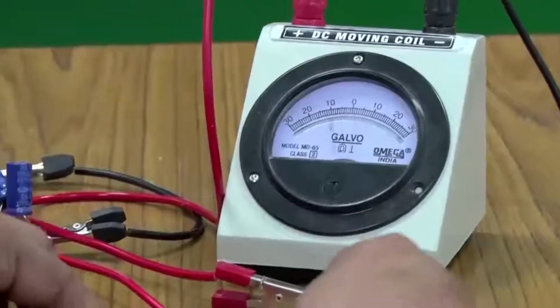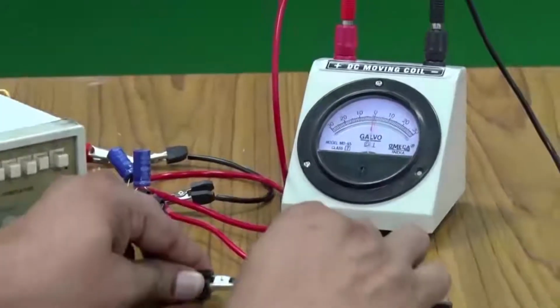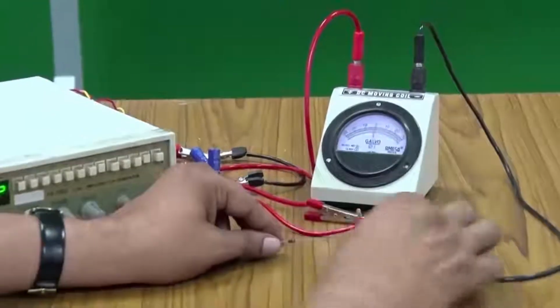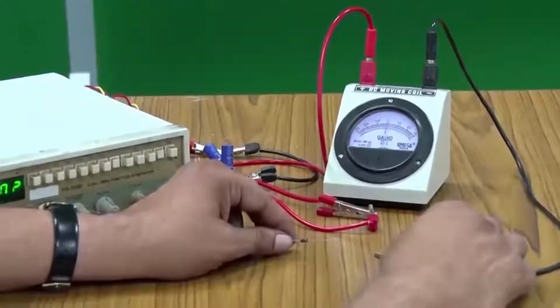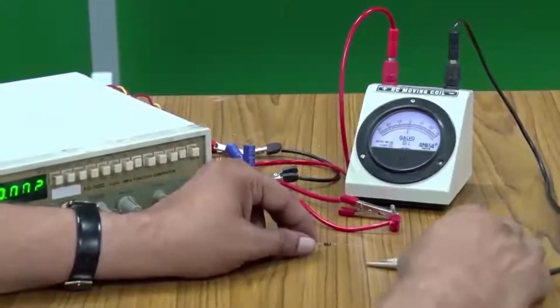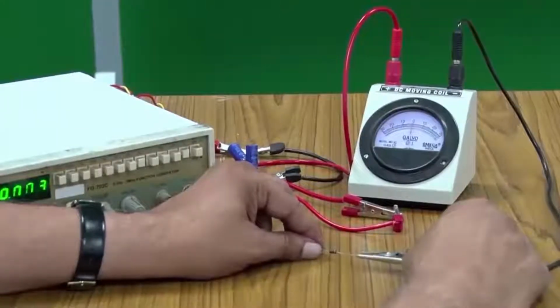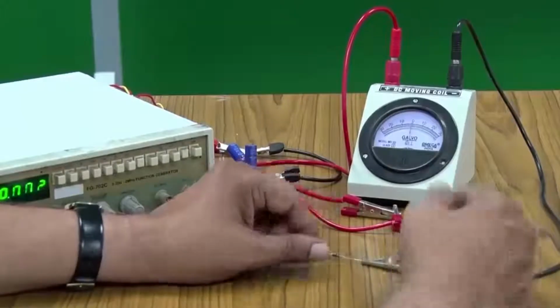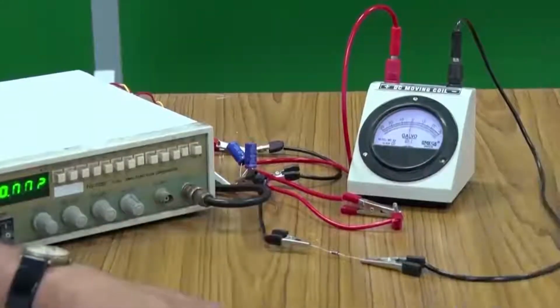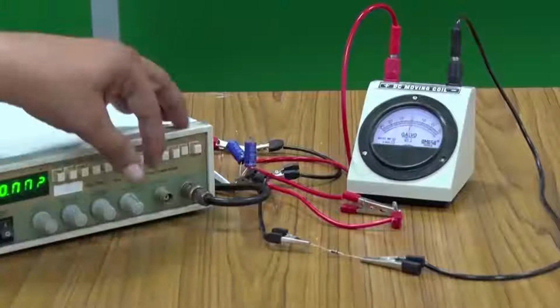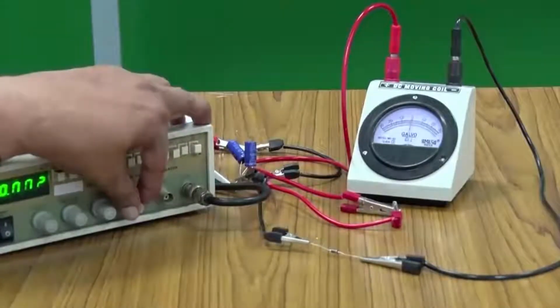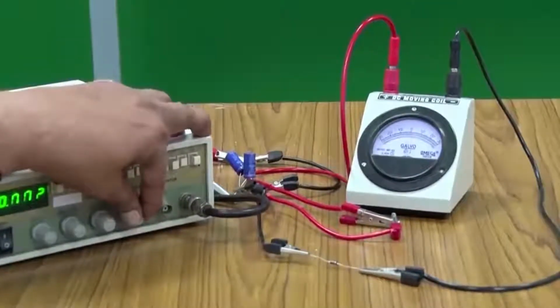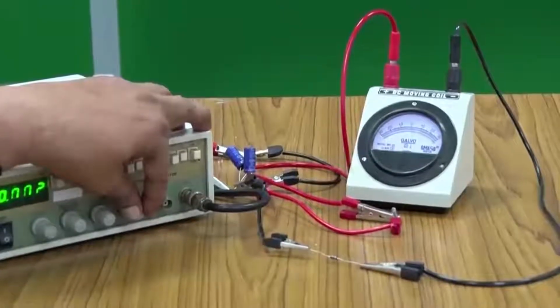So, that shows that this assumption that we had taken, that just forward bias and you have large current, is not true. You have to supply some initial voltage, after which that IV characteristic, the exponential part starts, only then it works. So, let me increase this voltage and you can see that yes, now it has started going.